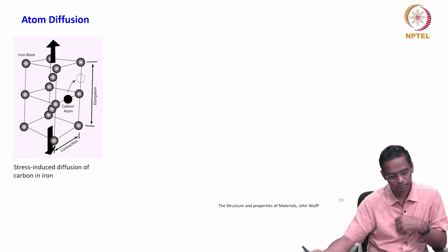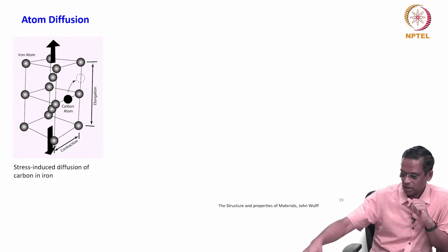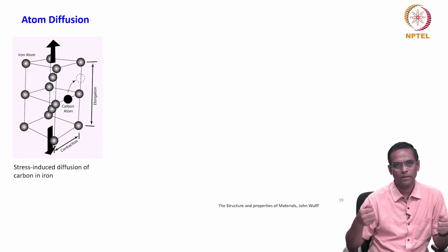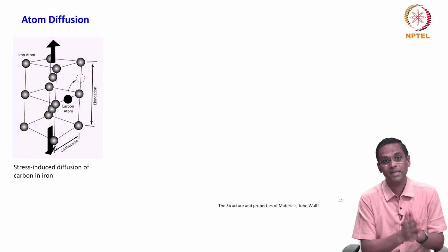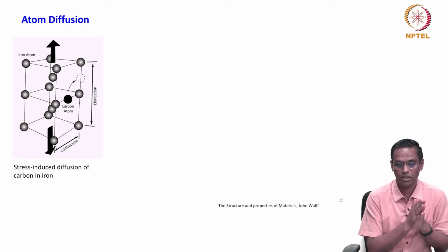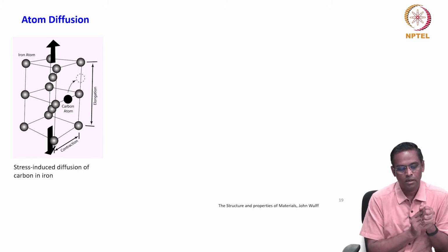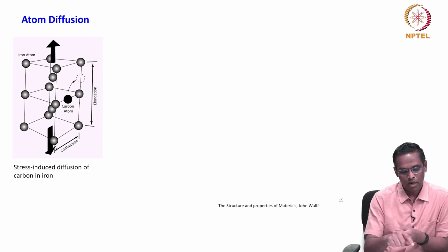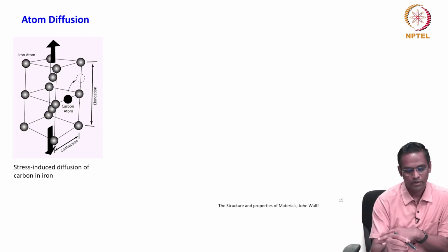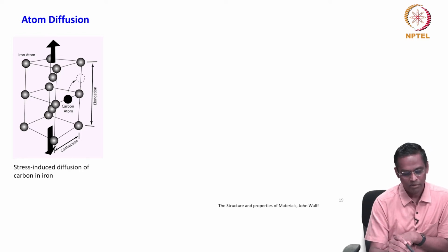Then what can happen? That is a general description. So, what can happen if you just stretch it? Now, please remember, we are talking about elastic deformation. We have not crossed that elastic limit. We are still in elastic deformation, thermoelastic effect, right. So, if you stretch it elastically, this axis will get elongated and the Poisson ratio effect will be there, so this will get contracted, right.